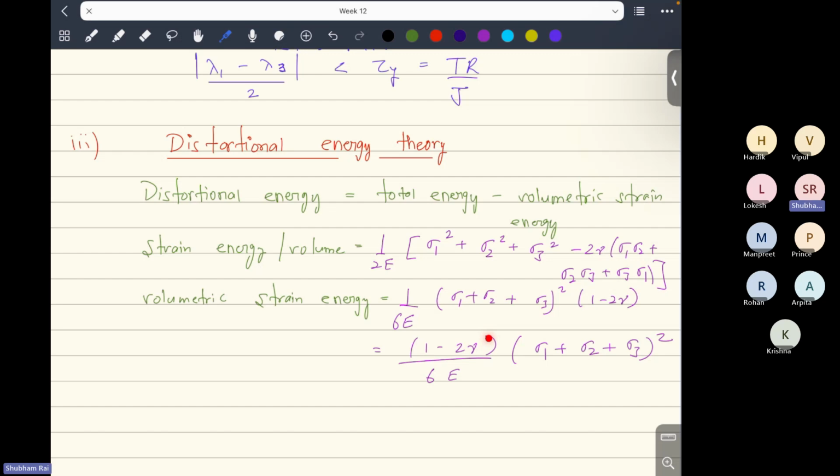in the high strain rate regime. Let's say a bullet is striking some structure, and that structure has a negative Poisson ratio. When the bullet tries to compress the material, the transverse direction will also get compressed, and the density of the material at a particular material point will increase.